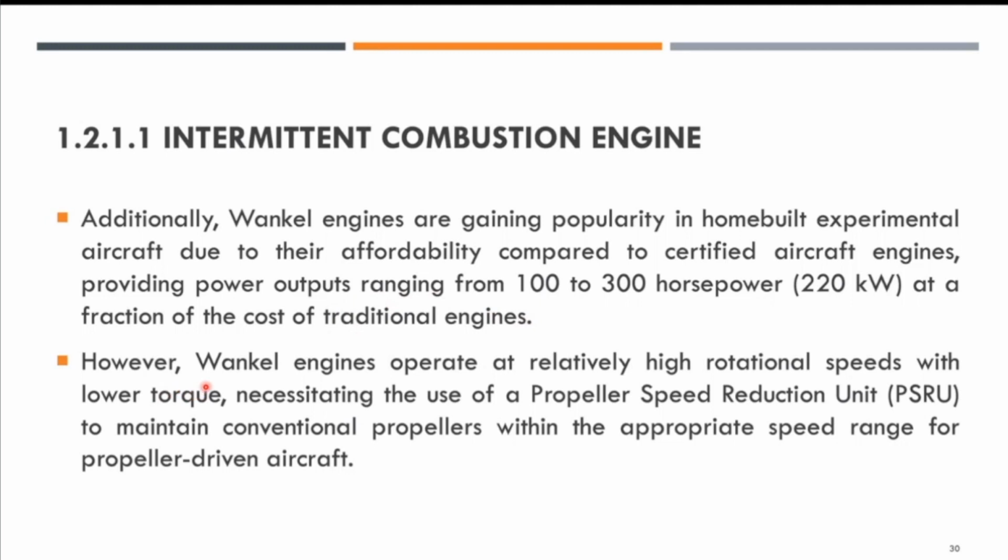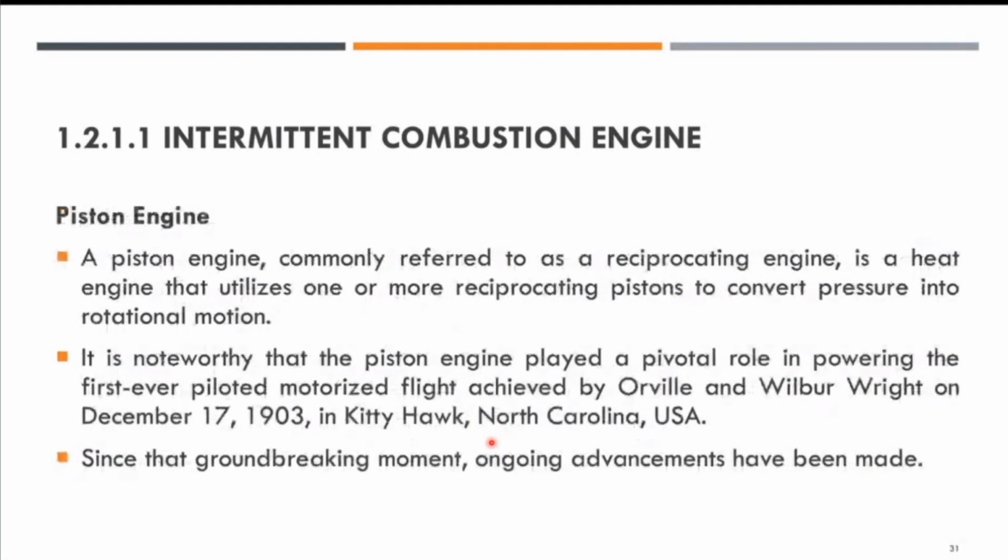Okay. However, the Wankel engine operates at relatively high rotational speed with lower torque, right? Which necessitates the use of a propeller speed reduction unit to keep a conventional propeller within the appropriate speed range for propeller-driven aircraft. Okay, so if you want to know more about the Wankel engine, you can try to Google what the advantages and disadvantages of the Wankel type of engine are.